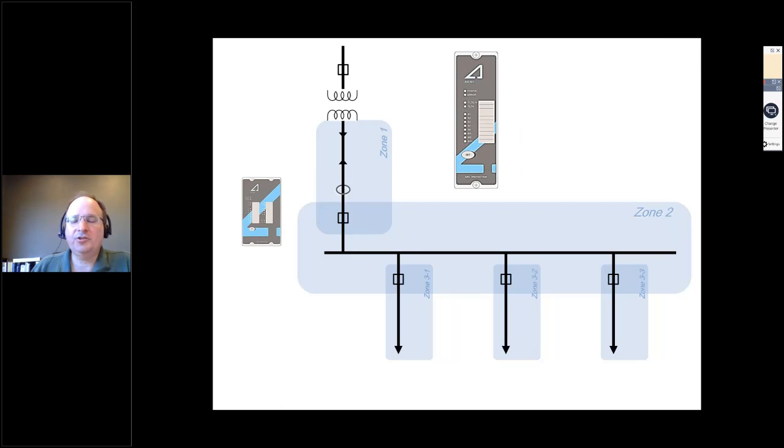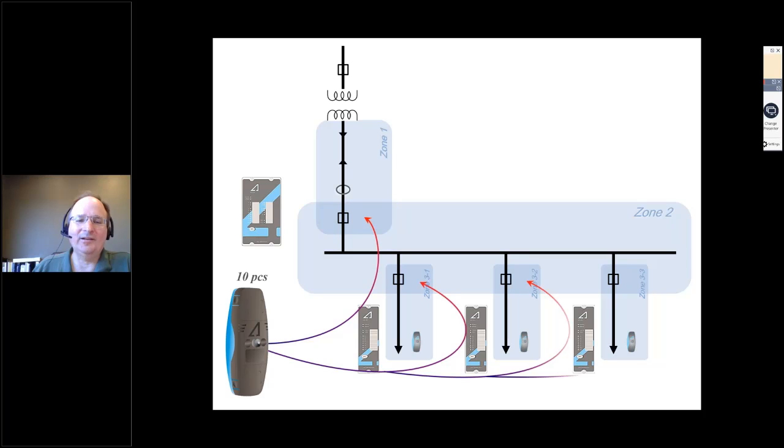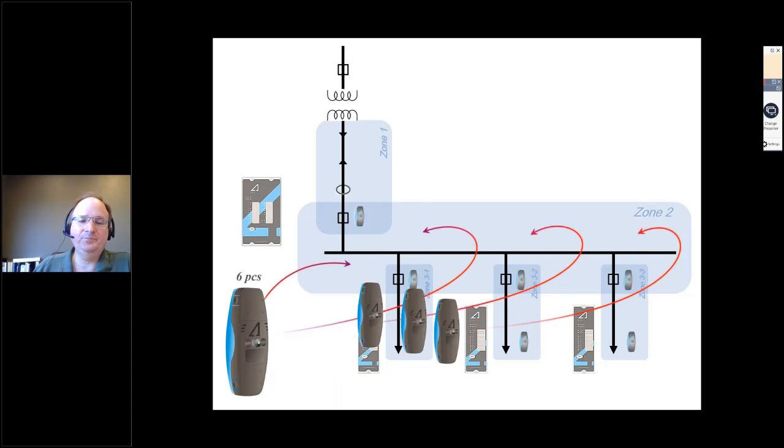And I'm showing our own Arcteq system here. This device here is a sensor relay. These sensor relays serve essentially as communication gateways for the sensors to communicate to the arc flash protective relay. We have multiple point light sensors in this case. Our system supports both point light sensors as well as fiber light sensors. But the models that I'm giving here today are illustrating the point light sensors. So we're going to install the point light sensors in the equipment.